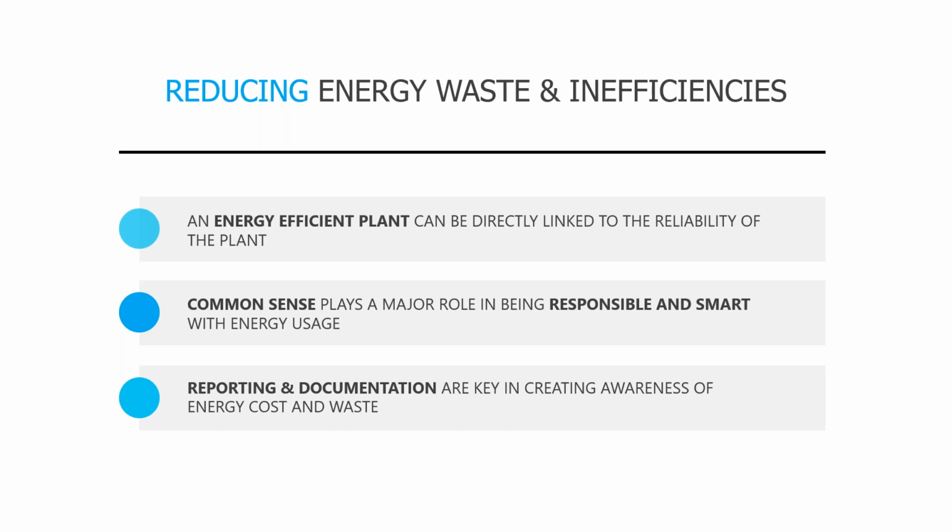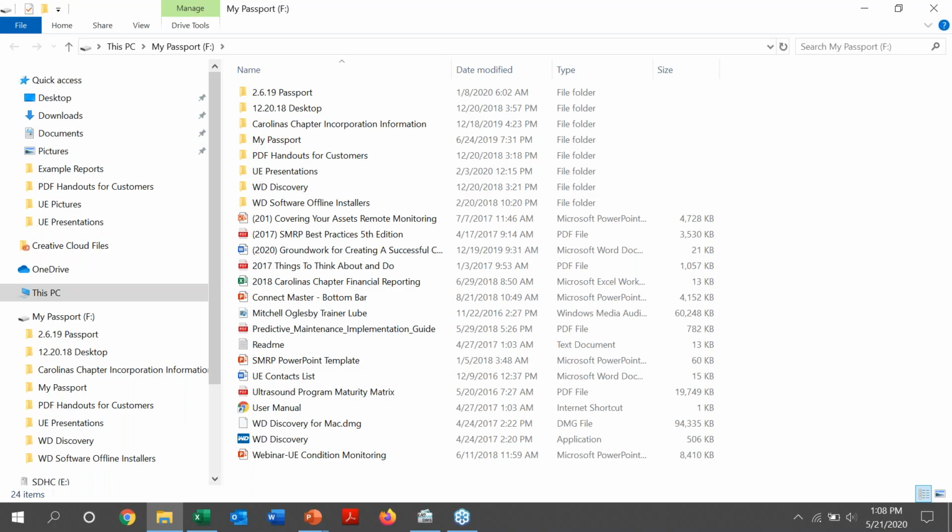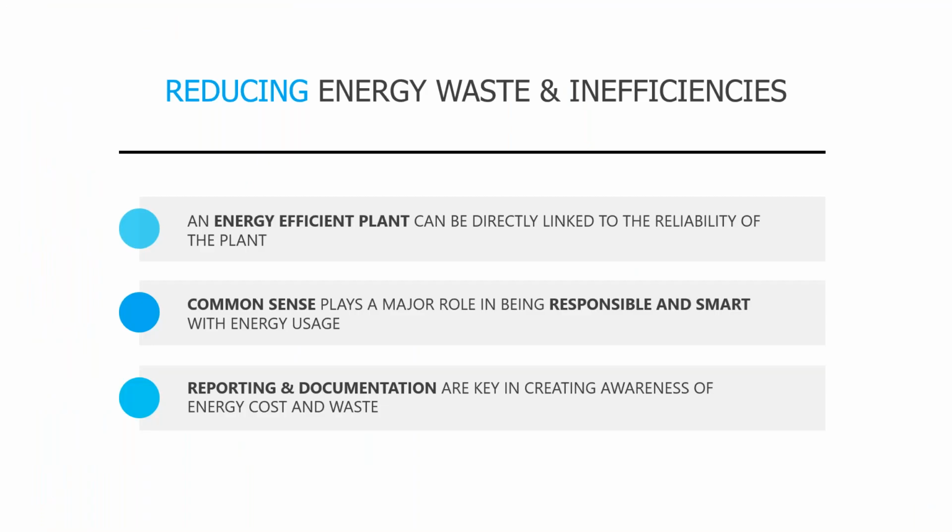It's the same way with energy. If we're out looking for compressed air leaks, for instance, instead of just saying, hey, we found 20 air leaks today, I'm going to show you how we can put a dollar amount to that. Same with steam traps. When you put a dollar amount to some of the things that you're doing in terms of your maintenance and reliability related tasks, then it helps to create awareness, it helps to create buy-in, and it really showcases maintenance as being an overall value instead of a cost center.